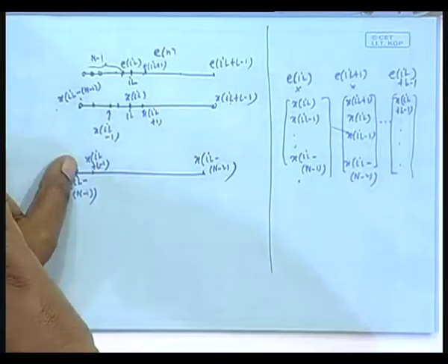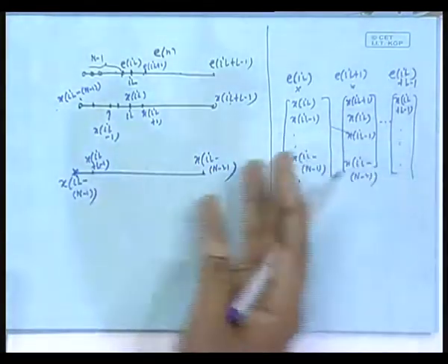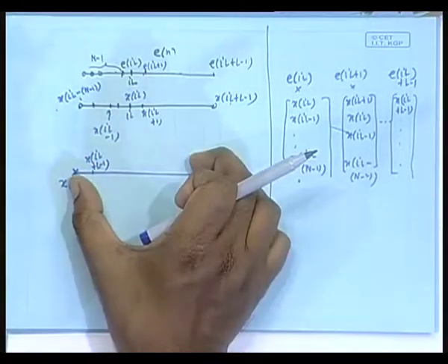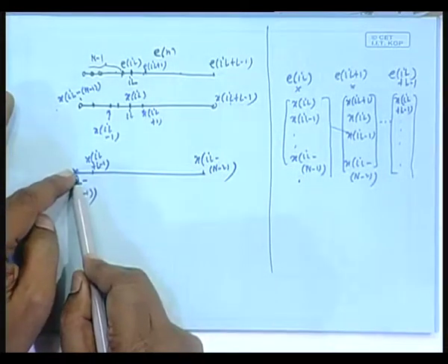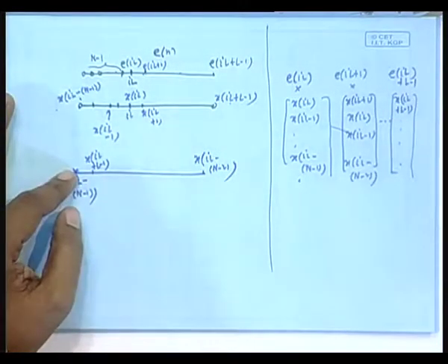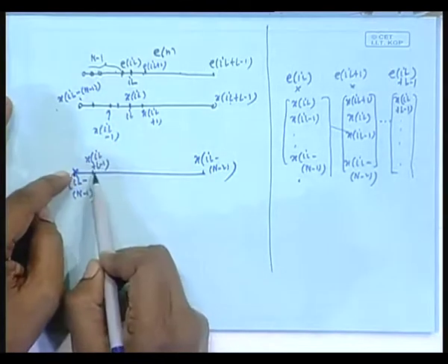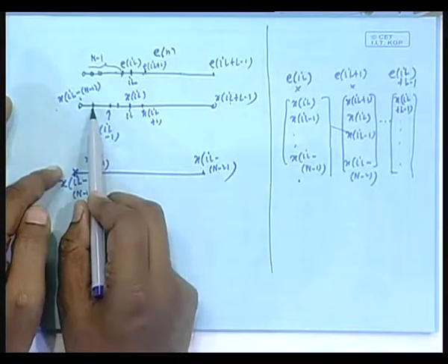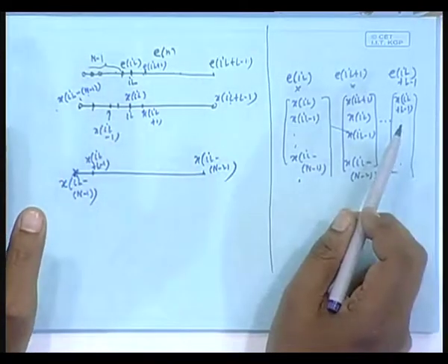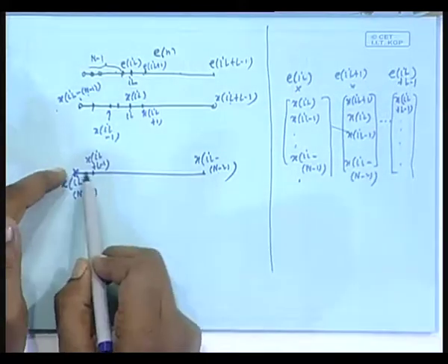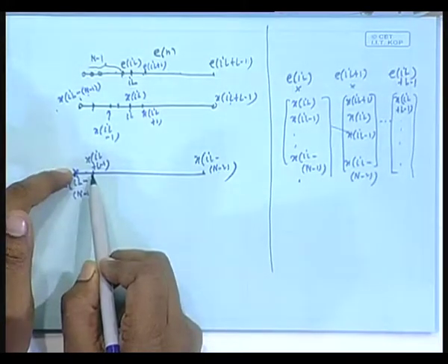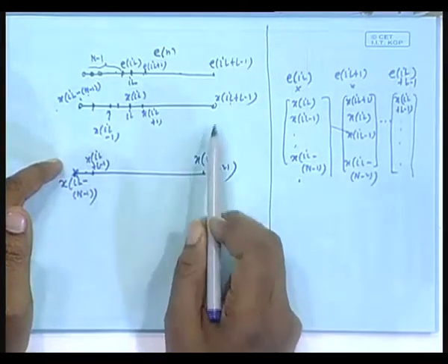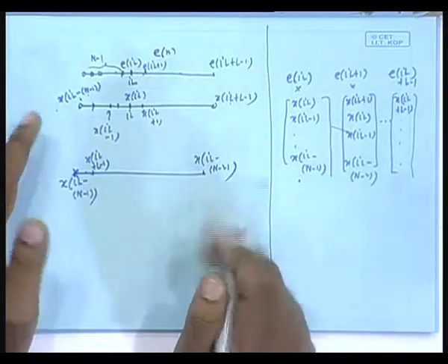I flip it, and then I make a periodic version of it, reverse. Whatever you see on the left hand side, that will come here. This guy will remain as it is. This will come to the left hand side. So, that is again by periodicity coming here, I L minus within bracket n minus 2. So, here it was n minus 1, n minus 2, that way. This was the immediate right neighbor, this will be the left neighbor, and that will come here. All right.